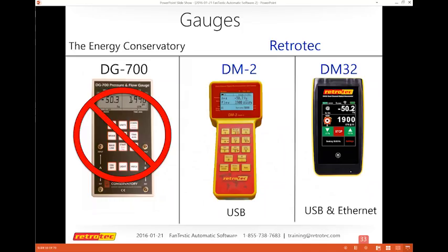So the DM32, hey Colin, can I get you to mute? Yeah, I just wanted to make a point on one of the questions that was answered by Nigel. He said, do the fans work together to create the overall test pressure within the building? Yes, they do. So if you've got 3 fans on the bottom floor, they all work together to create the pressure. If you've got a fan on the 3rd floor, it works together to create the total pressure.